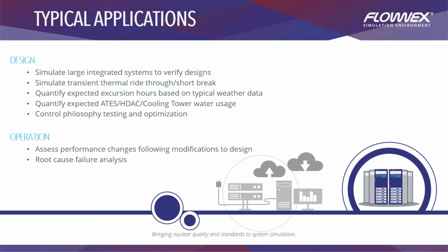Lastly, on the design side, Flownex is able to model the control logic in the system at a very low level. This allows us to capture the key performance of the system. And by modeling the control philosophy in detail, we can actually test different control philosophies in the system. So we could, for example, test different modes of switching pumps on and off to try and keep the pumps closer to their best efficiency point, and prototype and test that control logic in a simulation where it has no impact on the final performance of the system, but can be used to motivate design changes in your data centers to improve their energy efficiency.